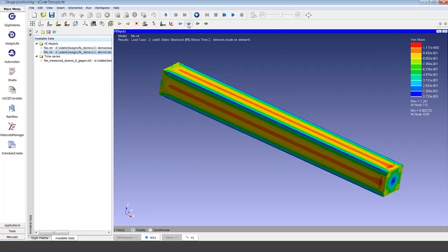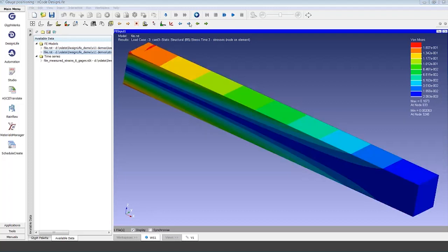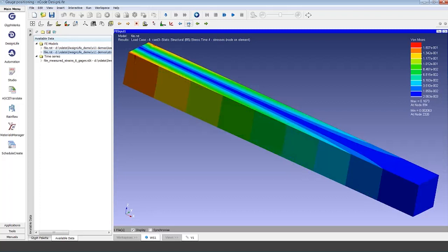Here's another one. The second degree of freedom of loading is the torsional case. The third one is bending, and you can see this would be bending on the z-axis, just based on the contour plot here. And then lastly, bending on the y-axis.